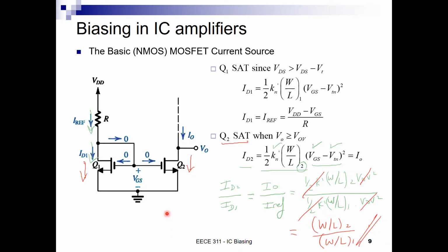And what we know is that on this side, the current can be determined by the value of R, and I can set those equations to be equal and find what is the exact bias and the current I'm delivering. Or for a desired current, I can fix R, and I can reflect this desired current to the other side. Anybody has a question about this mirroring action?